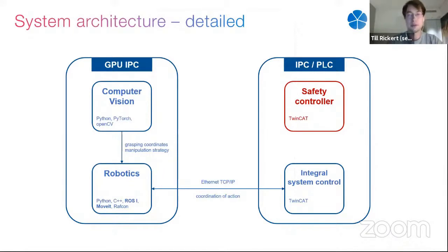It operates on a completely separate level from all other components and completely separated from ROS. This means no matter what ROS or something else tries to do with the robots or other components, if the safety controller puts the system into an unsafe state, nothing can move anymore. The safety controller has priority over all components, and this allows us to get an industrial certification for our product.